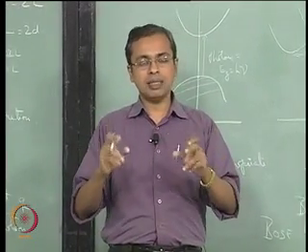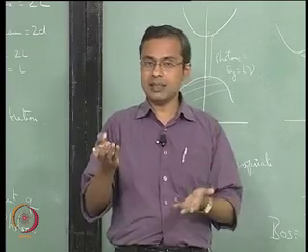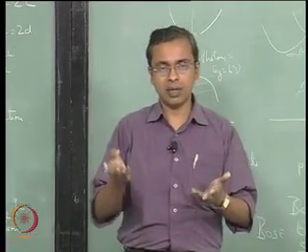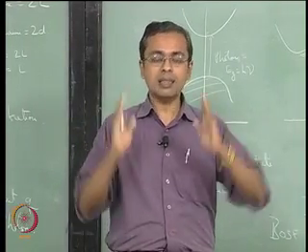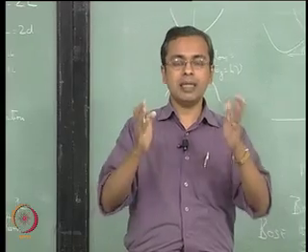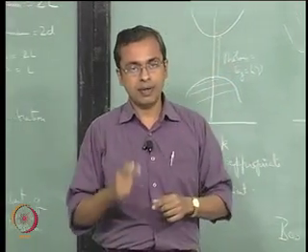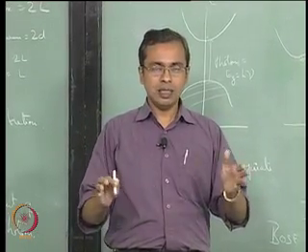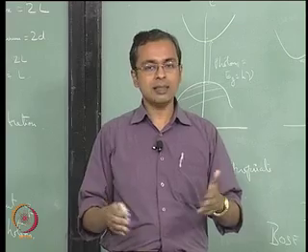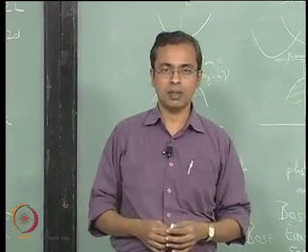The bandgap helps you decide which has more energy, which has less energy, and in some cases either of them might have a higher or lower energy when you compare a direct and an indirect bandgap semiconductor. Additionally, we also have to look at the probability that the transition will occur, and that probability is much higher when you look at a direct bandgap semiconductor. So with this we will halt today in this class, and in our next class we will look at superconductivity as a phenomenon. Okay, thank you.